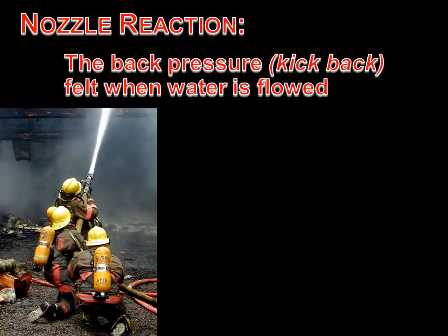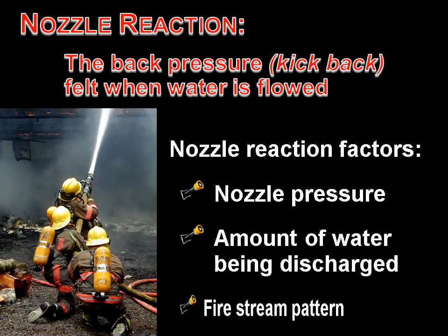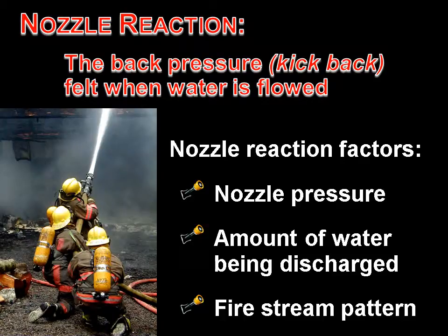Nozzle reaction. The back pressure kickback felt while water is being discharged from a nozzle. Factors affecting the amount of nozzle reaction: nozzle pressure, the amount of water being discharged, gallons per minute, and the fire stream pattern.